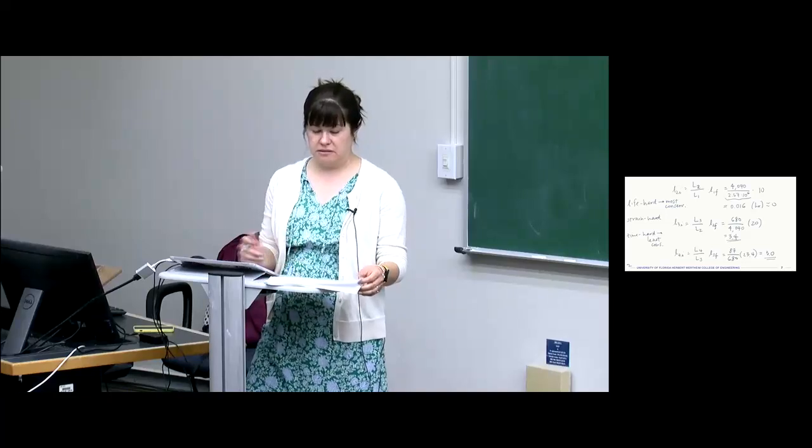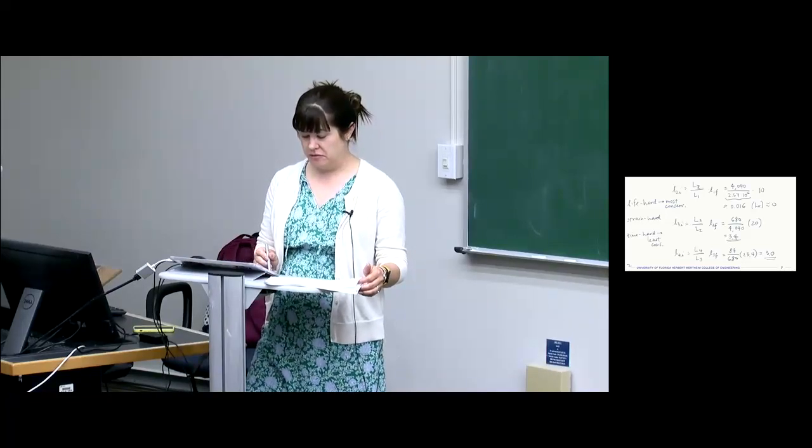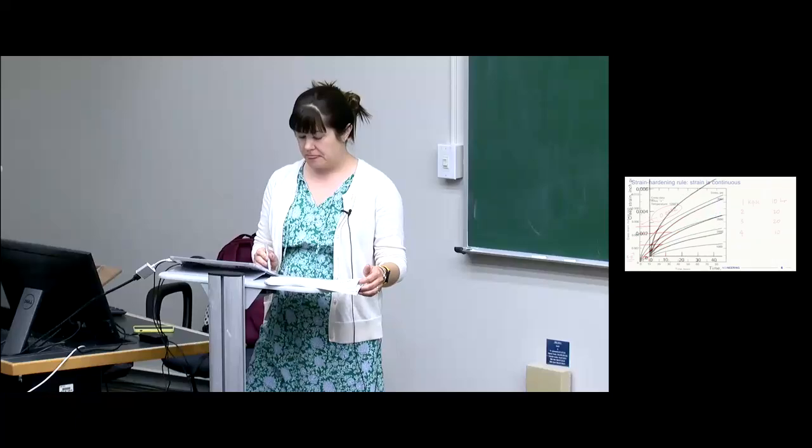And the answer is, it all depends on the material, unfortunately. So we're given that this is just some alloy X. We don't know what it is. We don't know if it's ferrous, non-ferrous, if it's aluminum, titanium, whatever it is, we have no idea. And so the approach would be to see if there's a general characterization of the material already as to what part of its history, whether time or temperature, has more impact on the creep strain, and then go with that method.